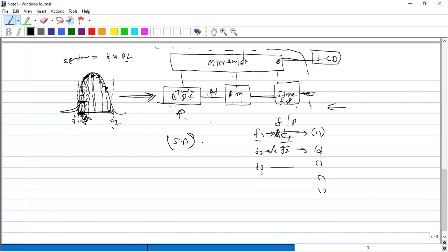In an oscilloscope, you can measure period, frequency, voltage like this. And advanced oscilloscopes are there. You can get the harmonics also using an advanced oscilloscope. We call them mixed-signal oscilloscopes. And sampling oscilloscopes are also there. Those are advanced oscilloscopes. Maybe using these, you can measure bit error rate and SNR also.